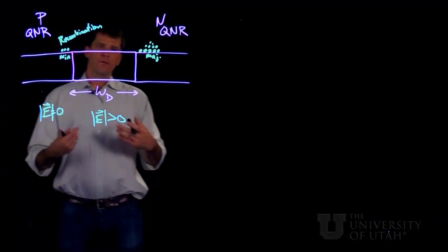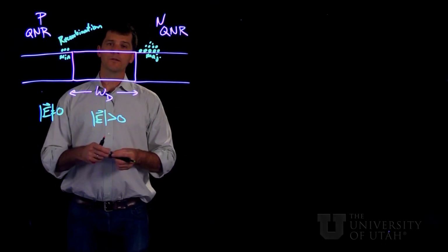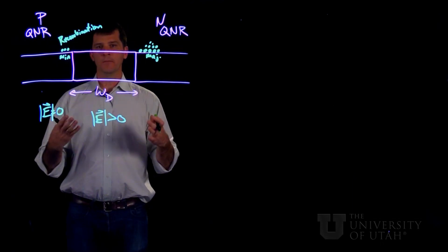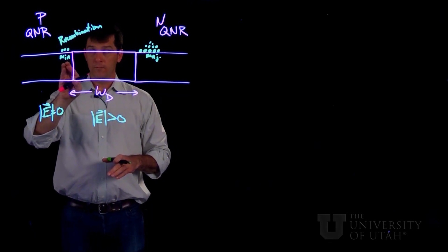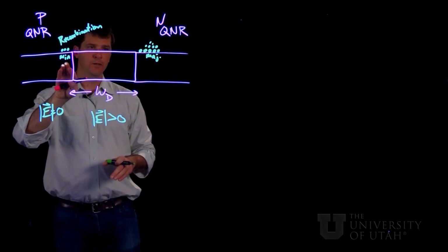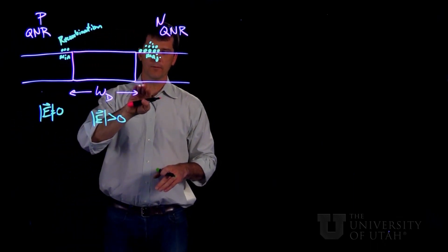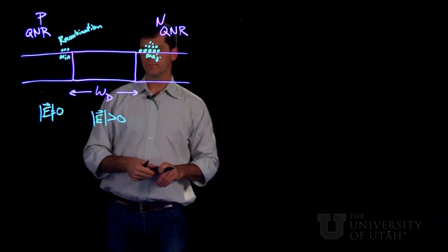So what we want now is to use our differential equations, which tell us about the minority carrier dynamics, at the edge of the depletion width in the quasi-neutral region for electrons, and at the edge of the depletion width in the n-type quasi-neutral region for holes, where they're the minority carriers.